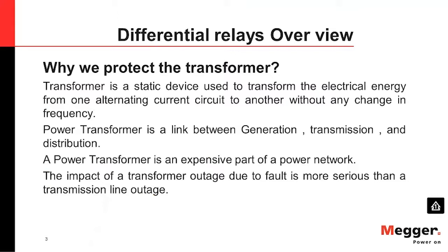Now, differential relays are for the transformer, to protect the transformers. And why the transformer? Why do you need it for the transformer? Since the transformer is the heart of each station, it's the heart between the generation to transmission, transmission to distribution. And it's the most, let's say, expensive asset in the power network. We should protect it and keep it healthy as much as we can.